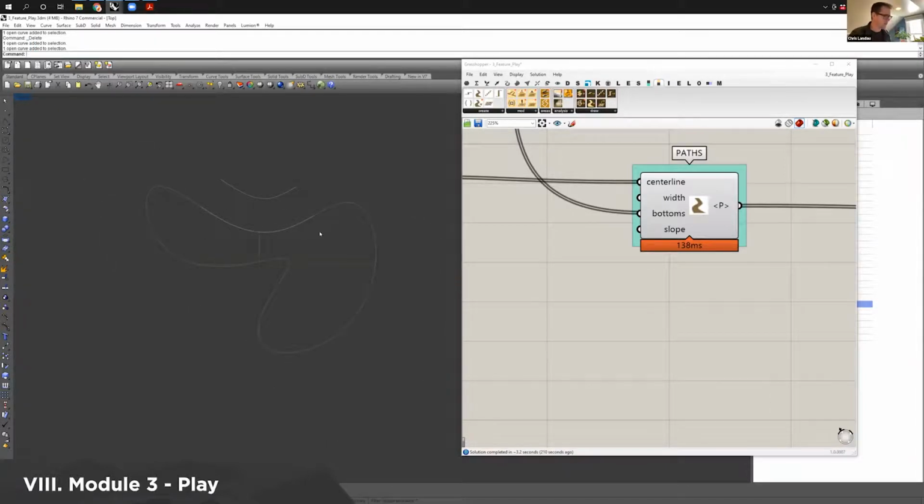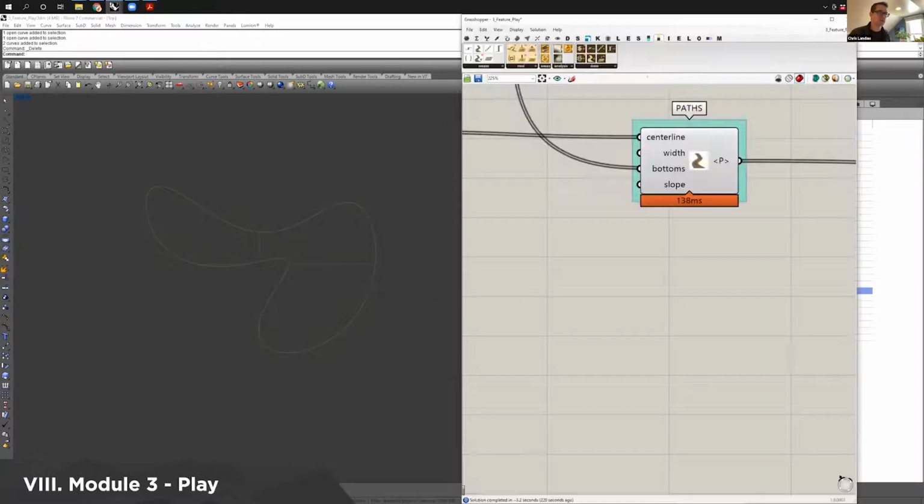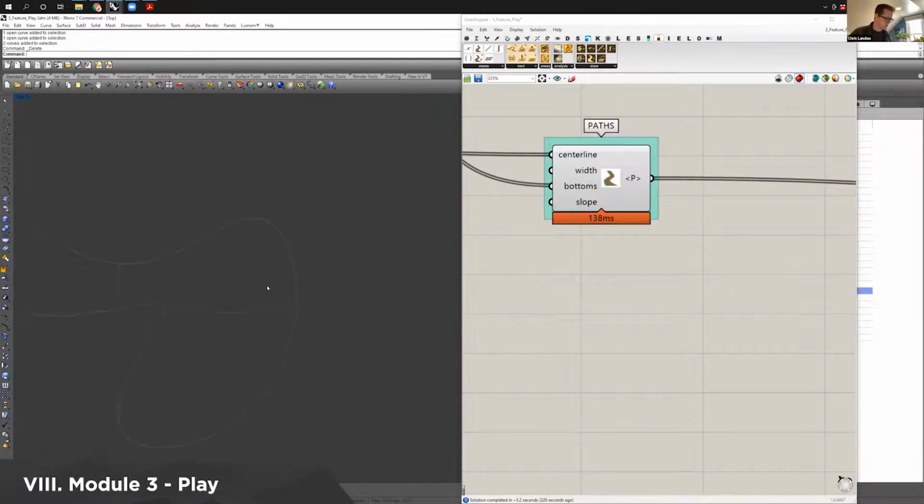We're going to select these, make sure we're working on the stair surfaces layer. I'm going to dupe border, select this surface, hit return, draw a line, select that line and type T for trim. Or well, T is one of our key commands. You have to actually type trim if you don't have that set up. Then click on that curve and it will delete the part you want. With trim, you always have to make sure to hit return when you're done. And then you delete the trim line because I don't need that.